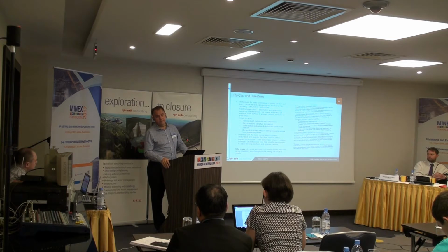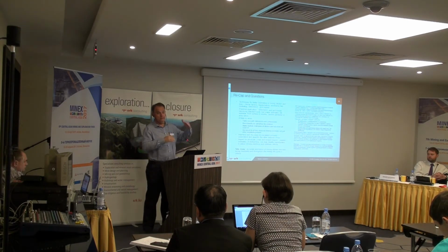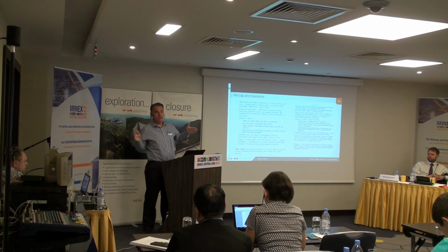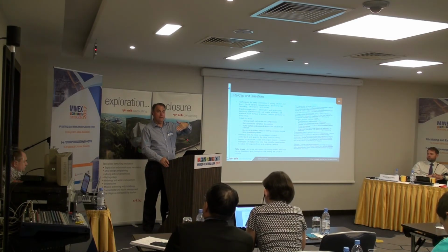estimate. It's an empirical method of estimating the degree of slabbing. So you have a design outline for a stope. This will predict, given the spans, say level interval spans, strike, stope width, you might have, say, 1-2 metres of material that will come off your hanging wall. You might have, say, half a metre come off your foot wall.